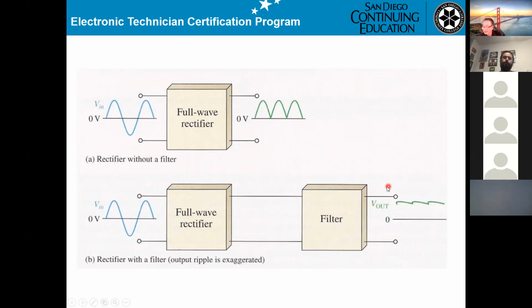That means the noise at the output here must be less than 10 millivolt. So the company has to design the circuitry so that the ripple or noise is less than 10 millivolt. The noise can cause problems for other circuitry, making it not work right.